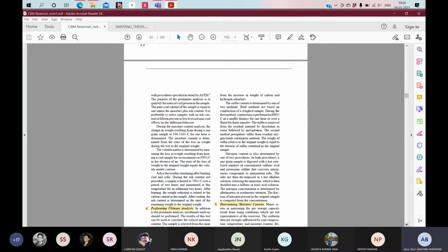And you have also seen that in the Langmuir equation, they are going to subtract the ash percentage A and the water content WC. So it is very useful to know about the ash and the moisture content. And as an added advantage, if you know about the ash content, then obviously you have some idea about the coal rank also. That's why it is very important. So please go through the process of the proximate analysis and the ultimate analysis.